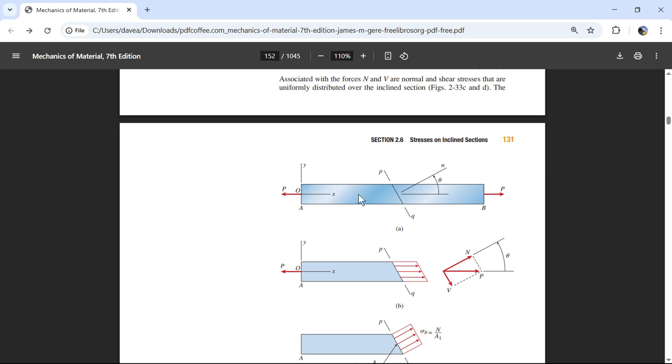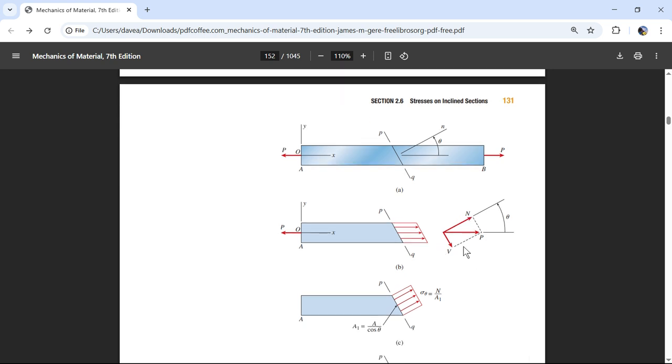So as we reduce that angle and kind of steepen that, what happens is that we get to a perfect place where, hey, this distance isn't too much anymore. I mean, it's only 1.4, square root 2 times this width. And then this shear force is now like 70% of P. And so that's kind of what happens.